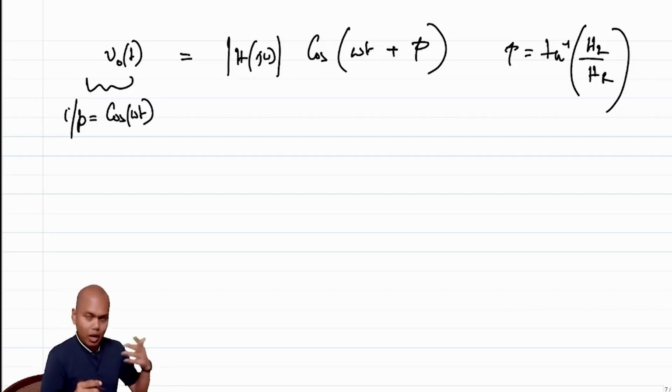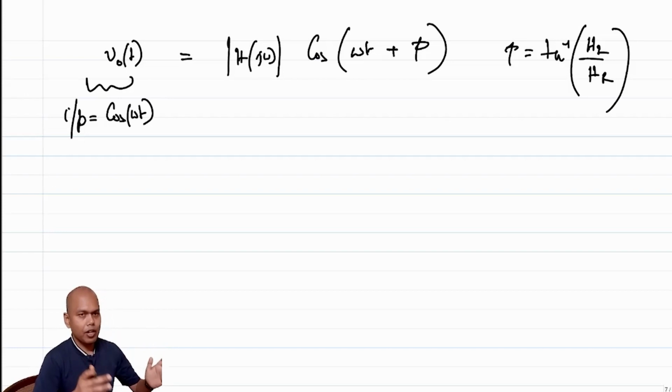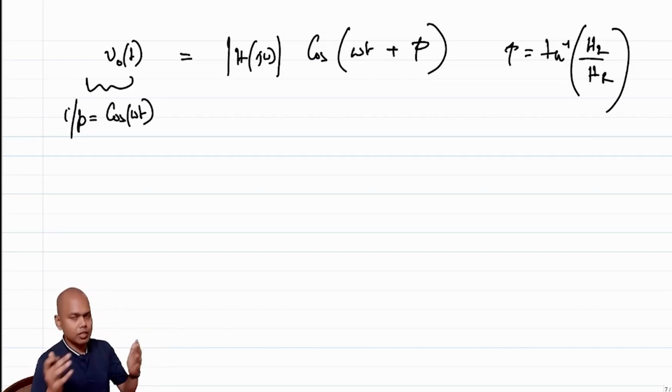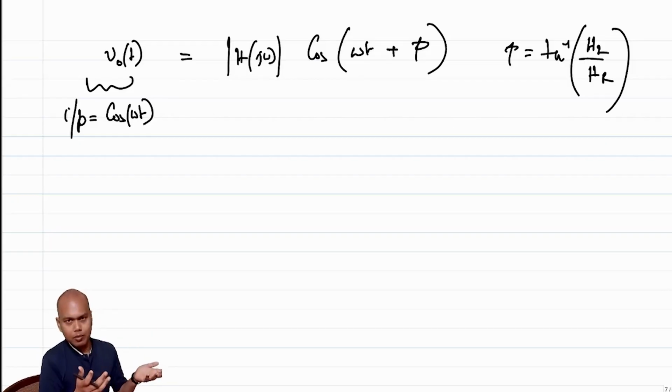Okay, so now why am I spending time on this? The reason is that sinusoids and cosinusoids are integral waveforms in any RF subsystem. We are going to have LTI systems, and sometimes we are not going to have LTI systems, but we are almost always giving sinusoids and cosinusoids as the input, and we have some transfer function of the system. Given these conditions, we should be very clear as to how the final output should look, right?